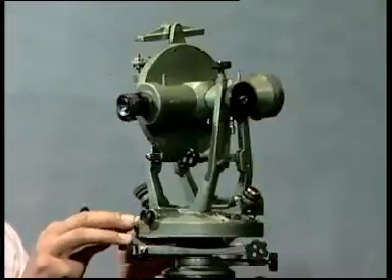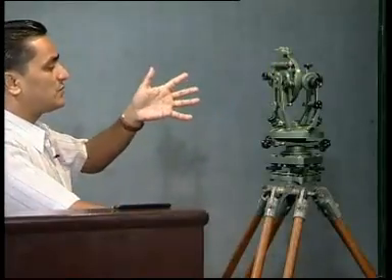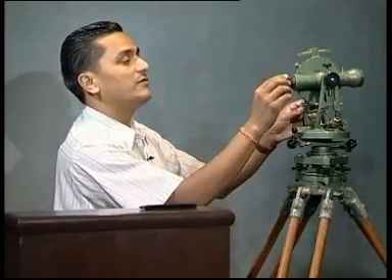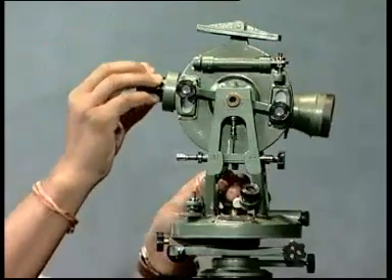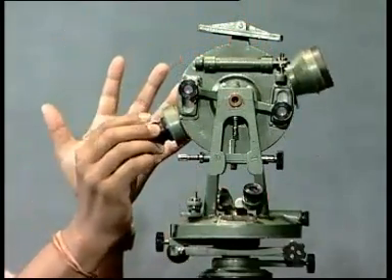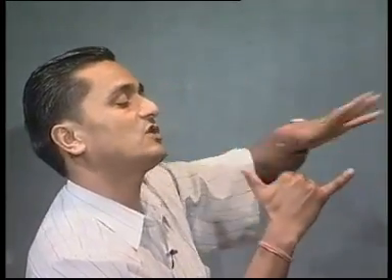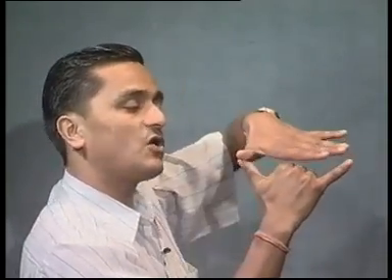Well, one more thing. In the case of the vertical angle measurement, that's the vertical circle and this is the vernier or the index frame. What happens if I rotate my telescope? In the case of the vertical circle, it starts rotating. With the rotation of the telescope, the vertical circle rotates, but the index or the verniers stay where they are. So these verniers form a line which is the horizontal line or horizontal reference. So I need to ensure that this is also horizontal.